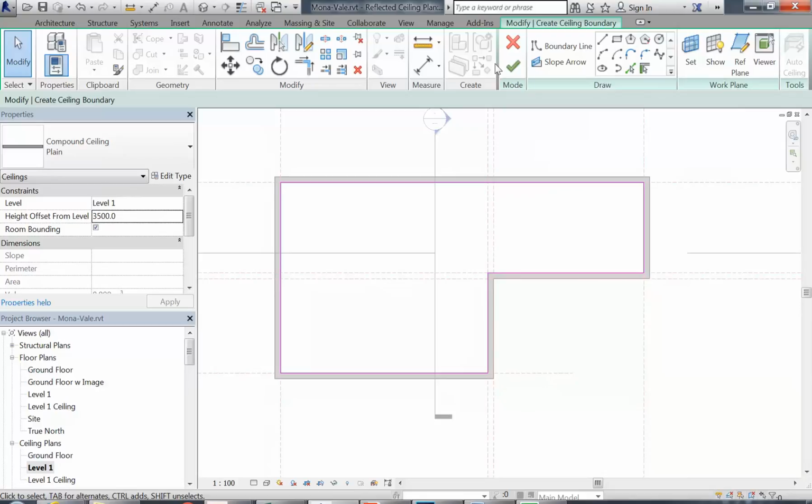Yes, layer. But still, it's still considered a ceiling. Okay. And how about overlap parts? Yeah, so you could use this ceiling tool for the main ceiling, and then where you've got a bulkhead that comes down, use model in place, what we were using last week, and make an extrusion, but you'd still set that as a ceiling, so Revit knows it's a ceiling. And I'll show you how to do that.